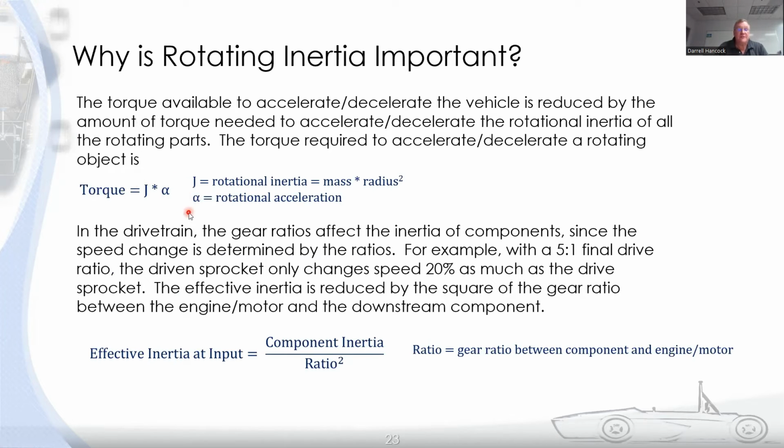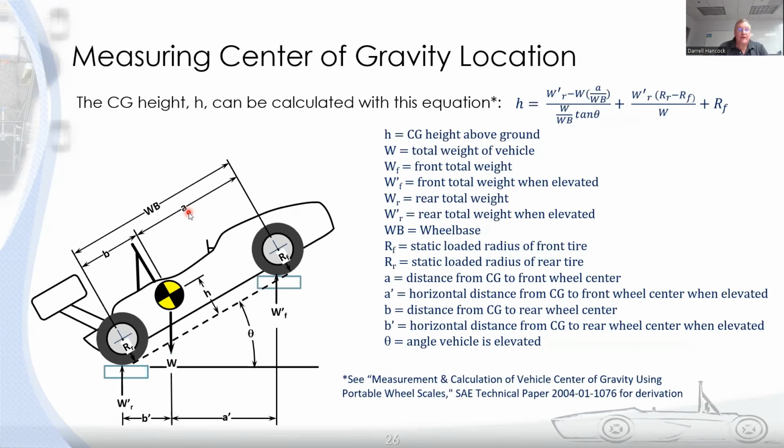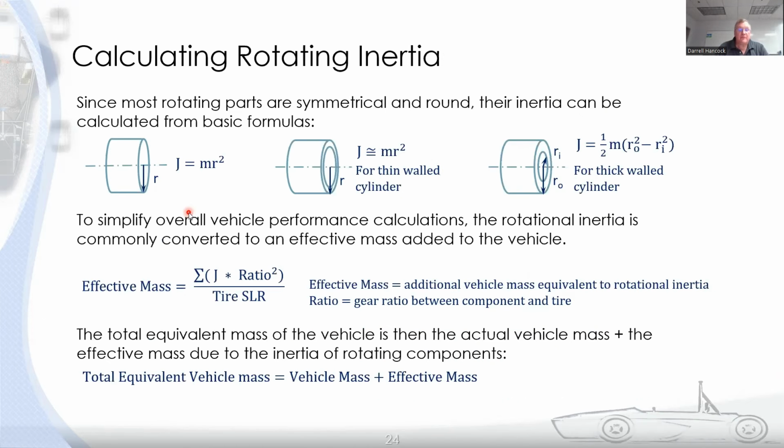So this term becomes much smaller, and your combined lateral and longitudinal acceleration will be tire limited, not engine torque limited, or I guess torque at the wheel limited. So I would say in both those cases, the safe assumption is just to use the vehicle mass.